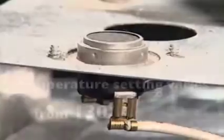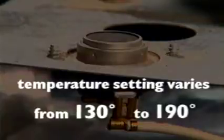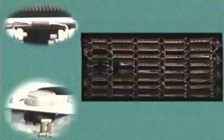The limit switch is a safety device with a temperature setting that can vary from 130 degrees to 190 degrees. If the temperature of the heating element begins to exceed the setting, the switch de-energizes the heating element. Another safety device is the fusible link. It protects the heating elements from burning out if for any reason the fan limit switch fails.